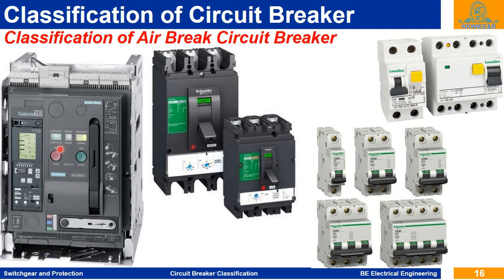Here you can see the actual pictures of the air circuit breaker. This is the air circuit breaker. On this air circuit breaker, the spring mechanism is there for closing and opening of the circuit breaker. This is the microprocessor based relay for overload and short circuit protection. Open and close push buttons are there.